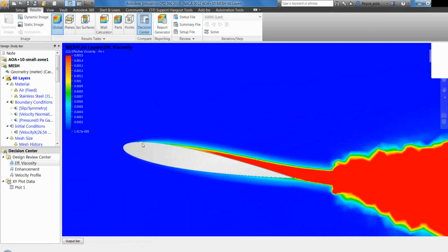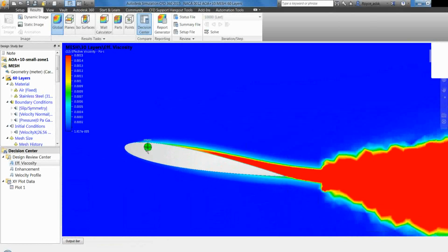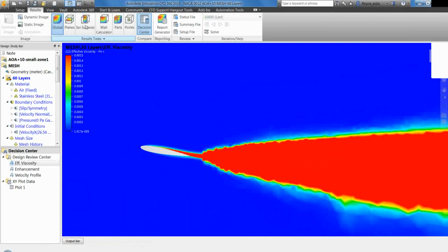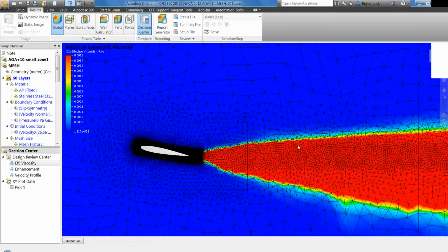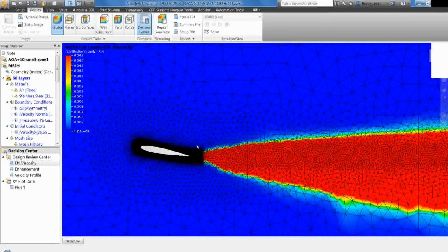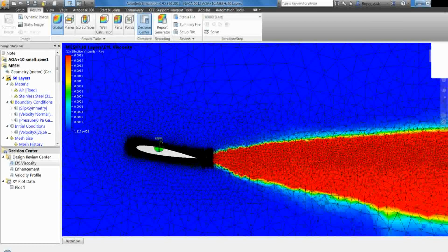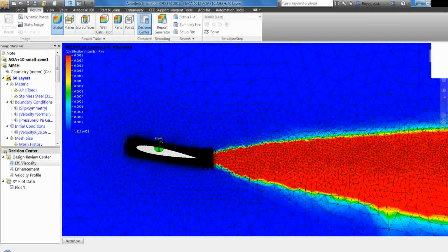So basically, if there's turbulence, then the effective viscosity is going to change. Okay. On the backhand side, the mesh becomes coarser, so there's a lot more diffusion going on in the results, and this is why it's spreading outwards. So if anything, if you were to talk about changing these results, I might actually add a bit more mesh on this wake side, but it probably won't change the results all that much.